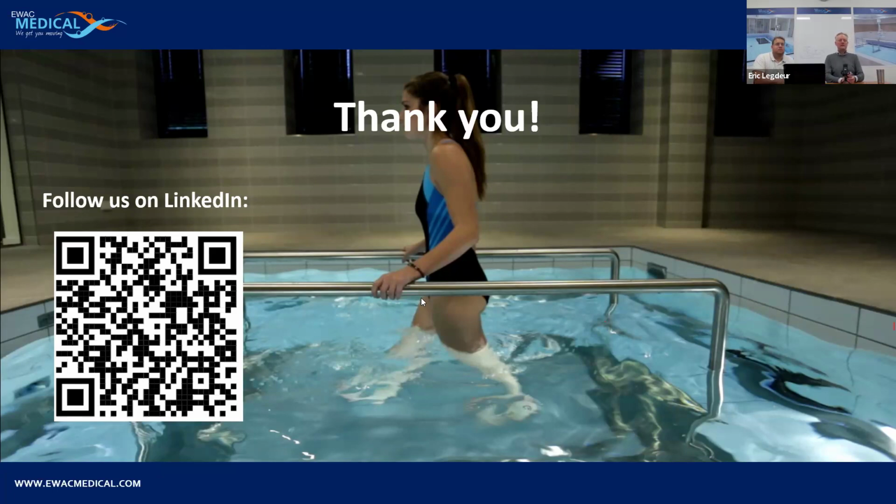Okay. Eman is asking, how can we determine the flow rate of water treatment in a hydrotherapy pool and what are the recommended dimensions for such pools? So the dimensions really depend on what you want to do with the patients, what kind of therapy you want to apply to the patients. So that is really on a case-by-case basis. What we do is we calculate with about 4 to 5 square meters that need to be available for every patient in the pool. So from that, you can calculate what size the pool should have.